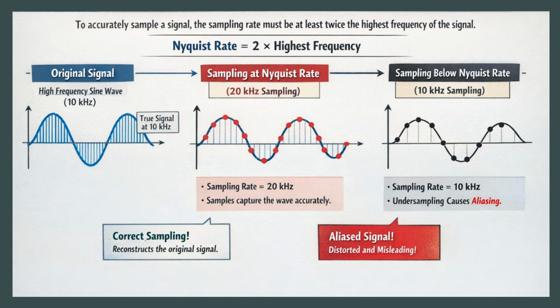Before starting the digital modulations, there are some fundamental techniques. The first fundamental tool is sampling and then quantization. Sampling is how you sample your analog message on the x-axis, meaning on the time axis. The sampling rate must be equal to or greater than twice the highest frequency, that is f of m or b of m, right? That is called the Nyquist rate.